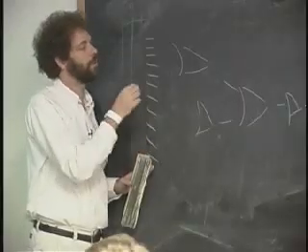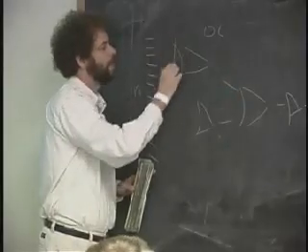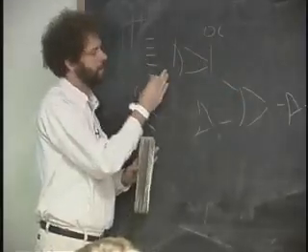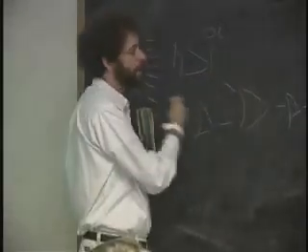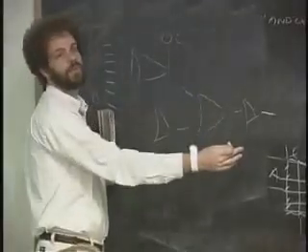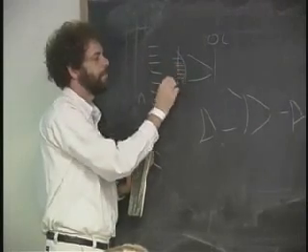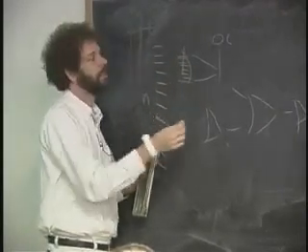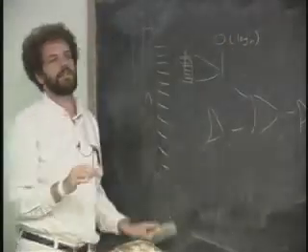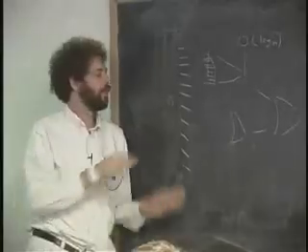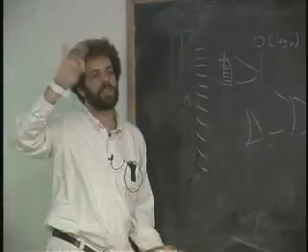And what does that mean? What's the order of growth of the speed of a circuit like this if each element has constant time? The bits come in here, they take constant time to go to here, constant time here, constant time here. So the height of the tree is equal to how long the circuit takes to work, which, if the number of inputs per gate is fixed and bound at some number, let's say 10, is order log n. So you cannot theoretically build an adder of a big number of bits n any faster than order log n, as n gets big.